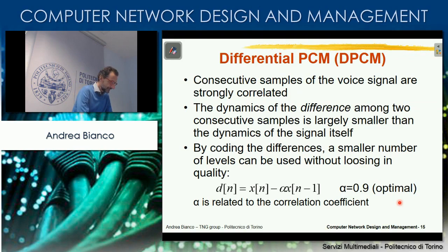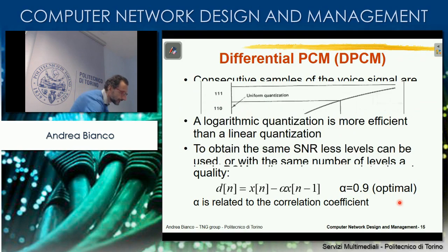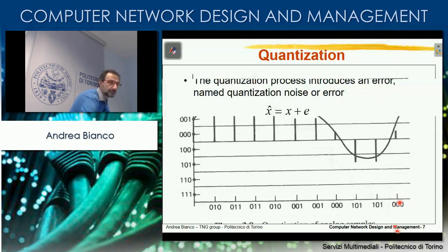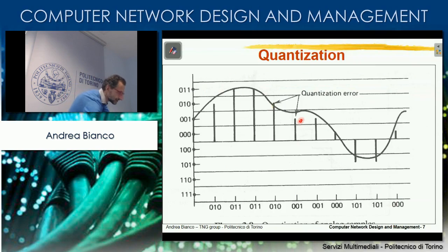difference between two samples, let's go back to this, where is it? Here. Consider, for example, these two samples here. This is a very ideal case. Sorry, the represented one here. Now these two have, in this specific case, exactly the same value. In this case, they have different value, but you see that the value of the difference signal, which is this minus this, the distance between the two, the value of the difference signal between two adjacent samples is much smaller than these dynamics.